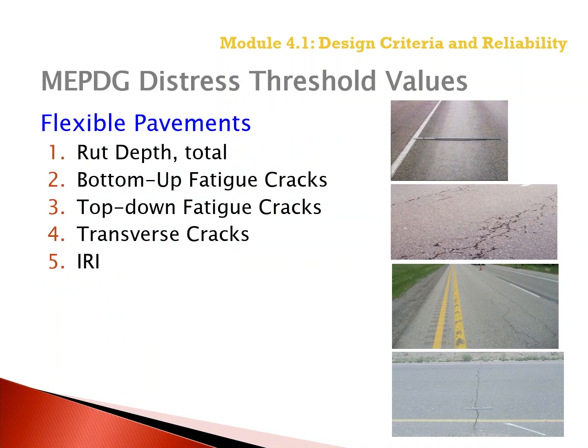The MEPDG threshold values, we basically showed those in the screenshots when we opened the software. And now we're just going to briefly go through each one as a reminder. So for flexible pavements, we have total rut depths, bottom-up fatigue cracks, top-down fatigue cracks, transverse cracks, and then IRI.